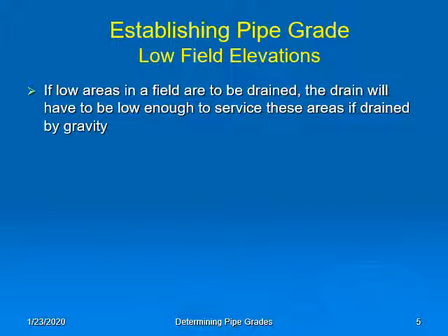We need to factor in the elevations of low areas and the distance from the main in order to provide gravity drainage. In some cases, a sump and pump are used to drain depressions where gravity flow is not practical.